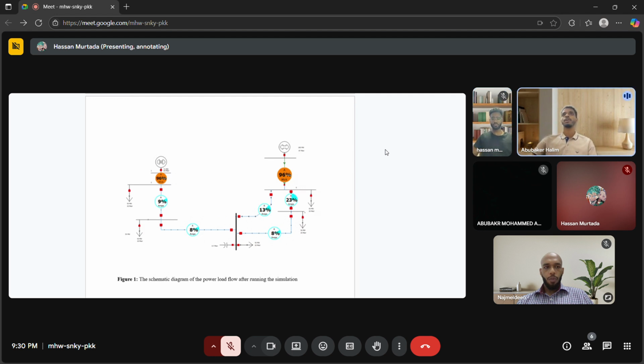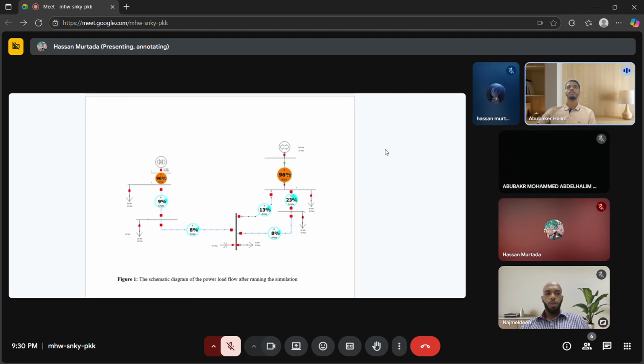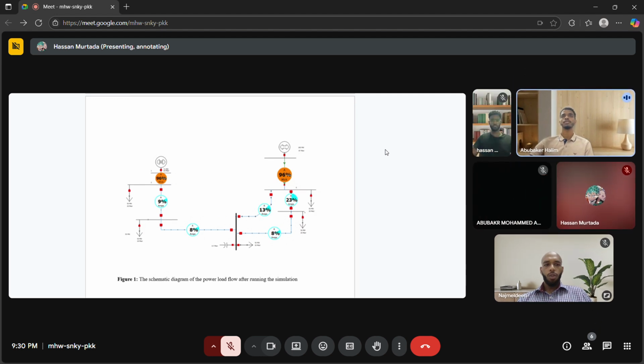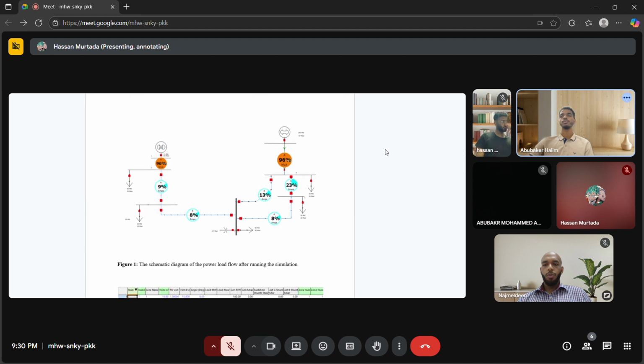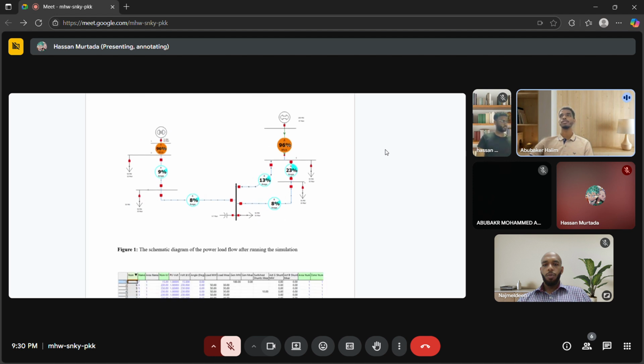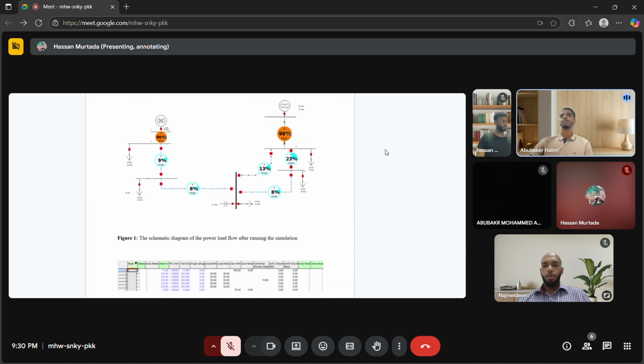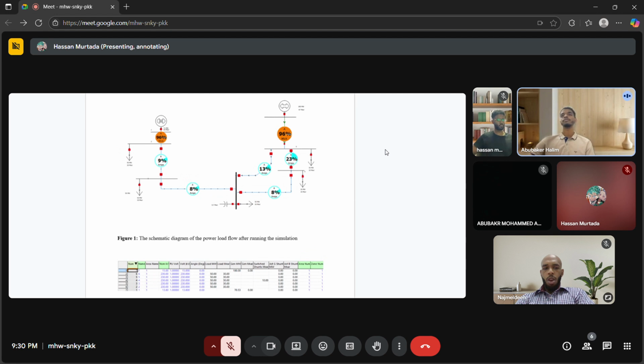Assalamu alaikum and hello, doctor. My name is Abubakr, and I will be talking about case one, which is the PowerWorld entry. So, once the system base was set, we began entering the components into PowerWorld. We first created the buses, then connected the lines with their impedance values. Then the transformers were defined with proper MVA ratings.